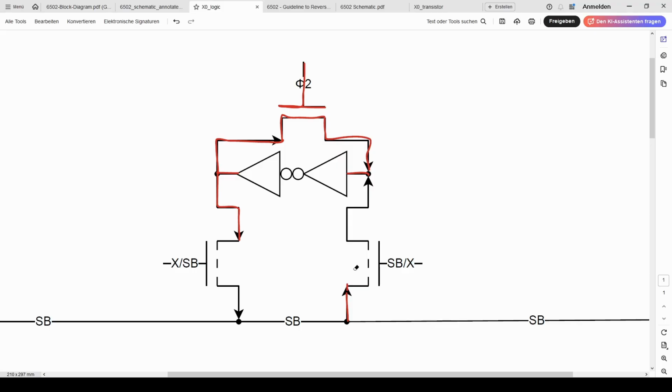Well, the reason for that is because we need some window of opportunity to override this. Because now, of course, we're saving a 1 here. And by the way, under normal circumstances, when this is low and there's already a 1 in here, I guess the residual electricity just lingers for long enough that it doesn't reset to 0. But the problem is, what if we then want to set this back to 0?